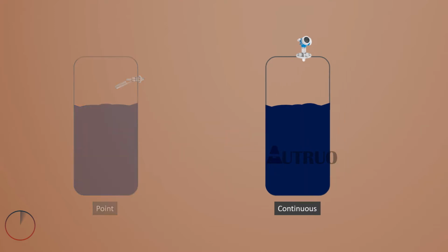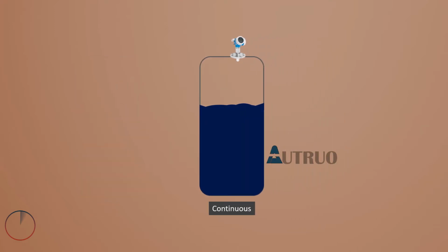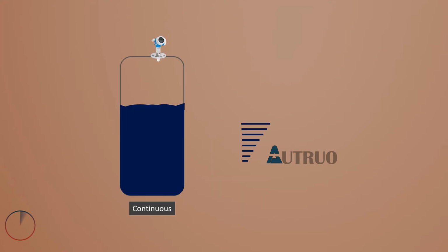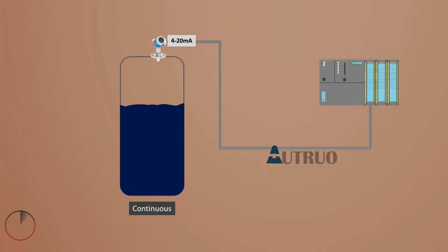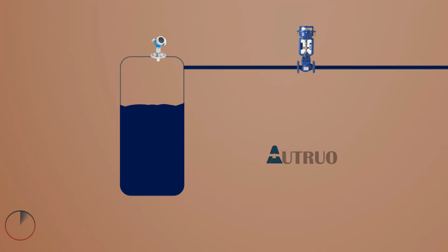Continuous level sensors, on the other hand, are more sophisticated because they provide continuous level monitoring of a storage vessel or container. They measure fluid level within a range rather than at a certain point. This means the level transmitter measuring range is not at a certain point. This instrument produces an analog output that directly correlates to the level within the vessel or container. The analog signal generated will be sent to the PLC. The varying output signal is usually linked to a closed process control loop. These applications will be discussed later.